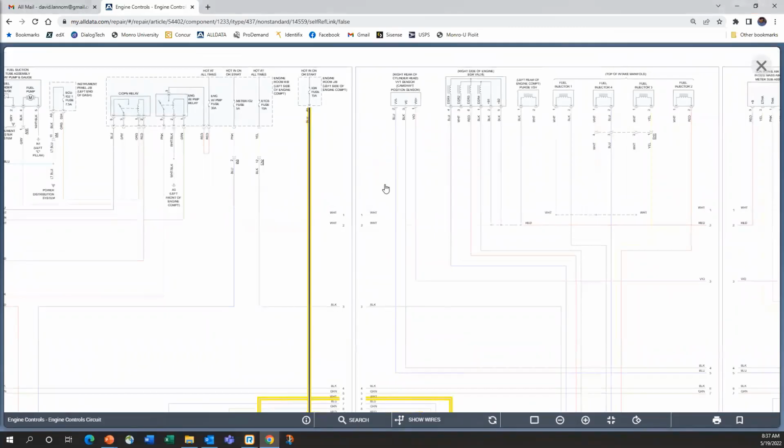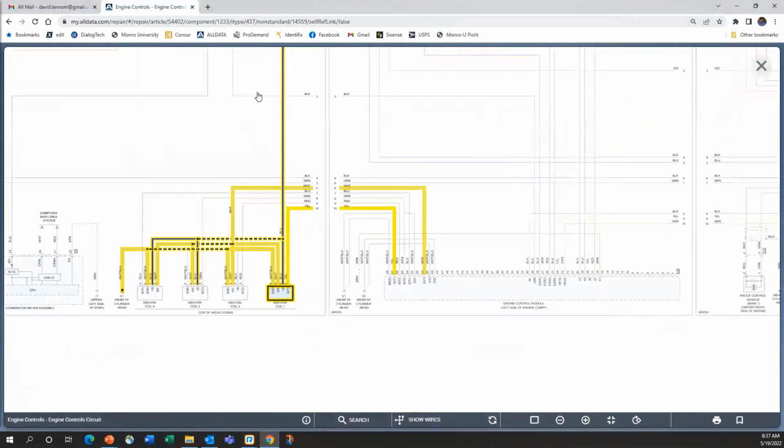I was looking for a source, and since we've already highlighted it, we can see the 15 amp ignition fuse. If we follow that path down, that is what's actually powering the coil. Now, when we take a look at the other signals, we can see that there is a ground, and that ground is pretty solid right there. And then we take a look at the load. So what was the load? The load was the ignition coil.